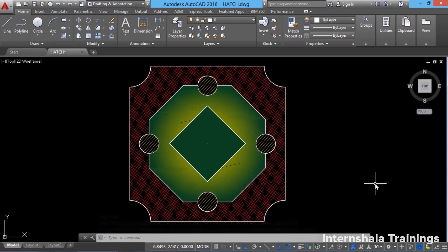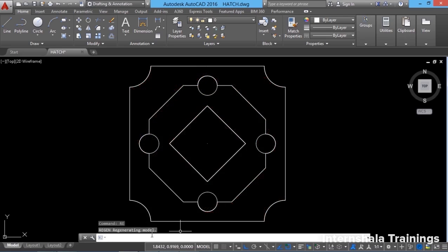In AutoCAD, you can temporarily suppress the display of hatch patterns using a command. For that, you can give the fill command. Fill mode can be in the on state or in the off state. Presently, it is in the on state. I'll just turn it off. Now, if you want the changes to be updated on the display, we have to give a regen command. So you can type RE. RE stands for regeneration. Now the display of hatch patterns is suppressed. Whenever you want to get it back, you can go to the fill command and turn it on. Again, you have to give a regen.